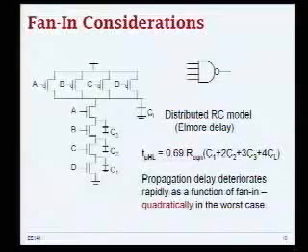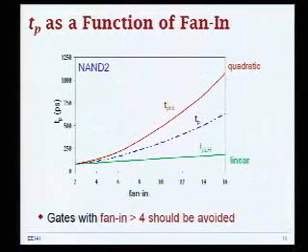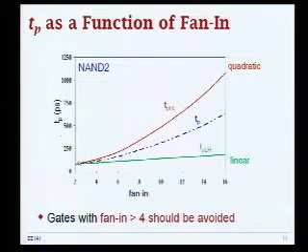All right, so let's go back to the slides. I have a plot for you to illustrate the propagation delay of this NAND gate that we've been analyzing thoroughly. As we mentioned, low to high delay is linear with an increasing number of fan-in stages, because when you increase the number of fan-in stages, you just increase the number of parallel branches. In the worst case, only one of those parallel branches is conducting and delivers current to the load.